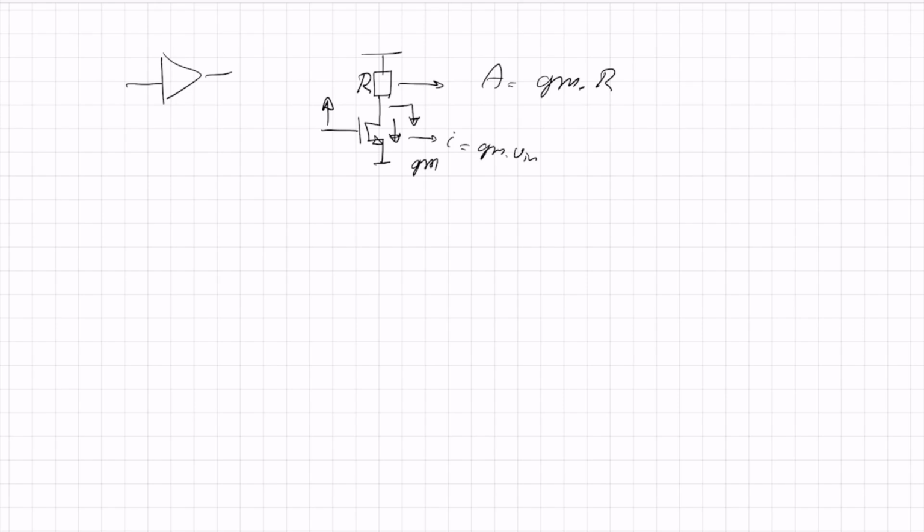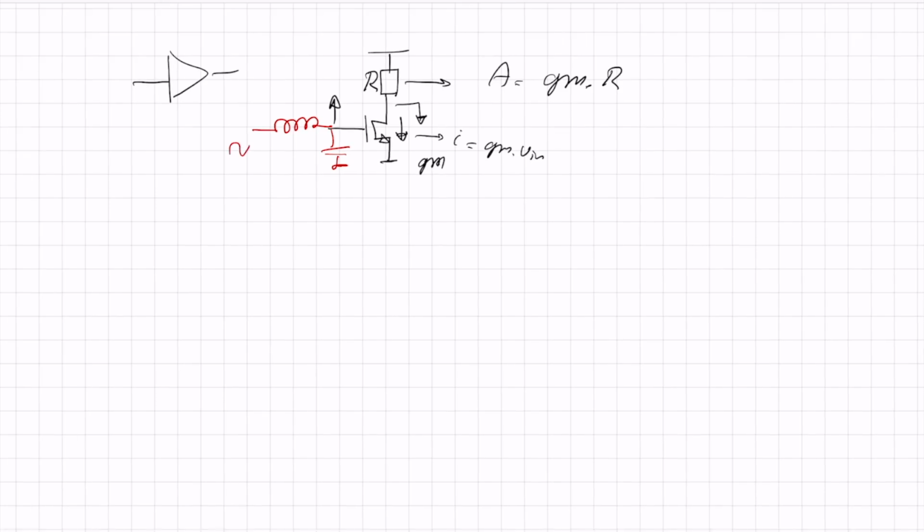For high frequencies at the antenna, we like a 50 ohm input, because the antenna is 50 ohm and the cable going to the circuit is also 50 ohm. So normally people add impedance matching, which is often an inductor and a capacitor. What that circuit does is give passive voltage gain at a specific frequency. If I have the resonant frequency in here, I get free amplification over here. That's because here I have 50 ohm and I bring it to a higher impedance, like in a transformer, and then I can get like 10 dB extra amplification.